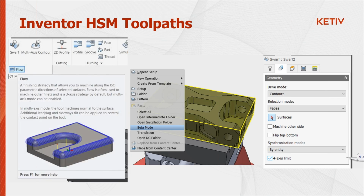Now, of course, in the multi-axis tab, you do have these extra toolpaths, right? So you have the swarf, which is the full 5-axis multi-axis contour toolpath, and the flow toolpath, which is fairly recent to the toolpaths here as well. So the ones we're going to focus on today are going to be the 3+2 positional toolpaths and the swarf and the flow toolpaths.